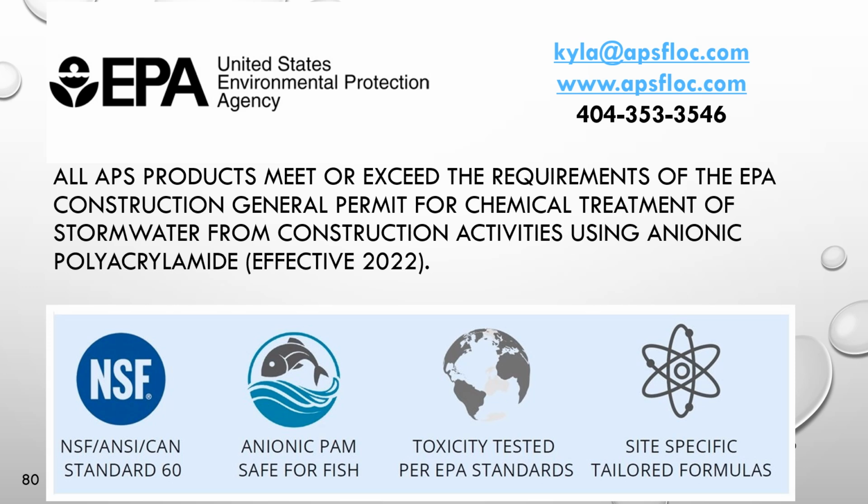Also, anionic PAM is safe for fish. Make sure that all products, all anionic PAM or any flocculants or chemical treatments that you're using for these types of projects have been fully toxicity tested. At APS, every single product that we have has been toxicity tested by a third party according to EPA guidelines: acute, chronic, 2 species, very, very thorough. And then again, you want to make sure that our products are site specific and you're matching the polymer to each site's soil and water.